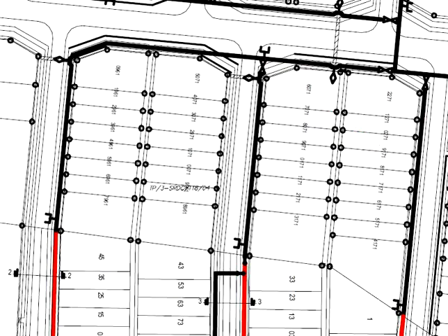You need to imagine it is nearly impossible for the water pipes from the fire engines to pass through the building units, reaching this unit here. Therefore, when we are quantifying the clear distance between the fire hydrants, we are talking about the access distance, not more than 90 meters.